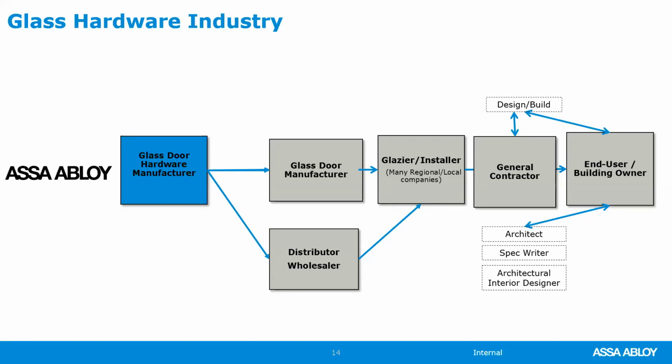They put the appropriate prep holes in the glass for the hardware. And then once all of that's done, they put it through a tempering oven to get a finished piece of glass, or a monolithic piece, that's ready to receive hardware or in the door to be built.